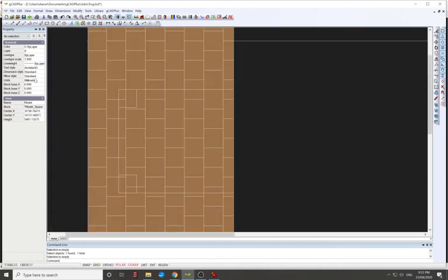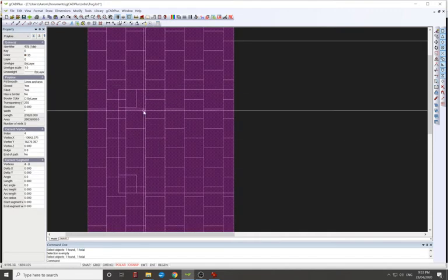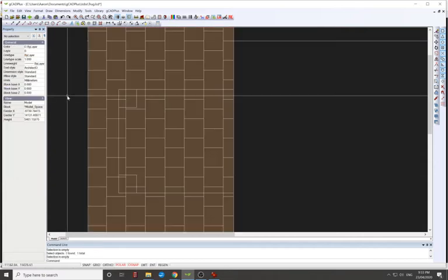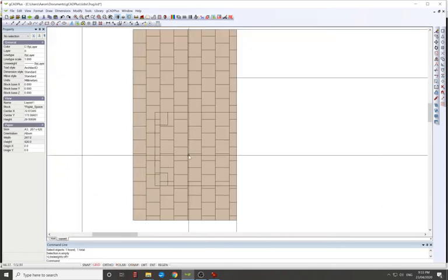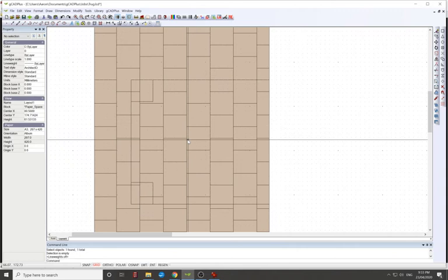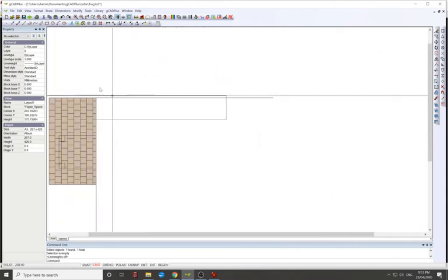So we'll just go to model. We'll look at that trend. Click on this filled polyline area, not a hatch. Go back to our, where is it? Transparency. Yeah, we'll just click it down to 125. Enter, and you can see it's dropped off a bit, and those lines are more prominent now. It just looks a bit better. So that's our paving.